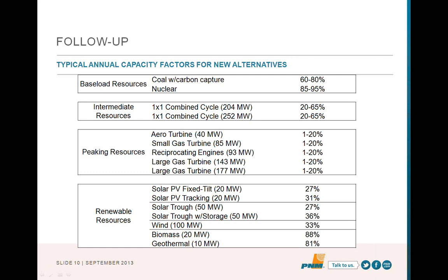Yes, but could you expand on that with regard to solar trough? Yeah, solar trough is a solar thermal technology. So in that case, you're taking sunlight and converting it to heat, and then letting the heat convert it to steam. The advantage of a thermal system like that is it's not as instantaneously reactive to whether the sun is shining or not, so you have a little bit of a buffering effect there. And the other thing with trough is generally the trough systems look more like the single axis tracking systems. The designs I've seen tend to try to track the sun, so you get the same kind of advantage that you get with single axis tracking. So that's the kind of technology detail that we're thinking through when we make that assignment of what its capacity on peak is.